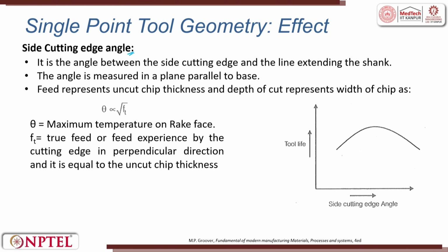When we talk about the side cutting angle, it is the angle between the side cutting edge and the line extending the shank. Side cutting edge, if you go back, you can see the angle is measured in a plane parallel to the base. Here the feed represents the uncut chip thickness and the depth of cut represents the width of the chip.